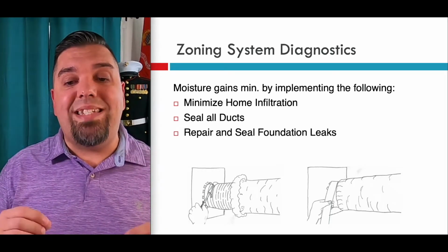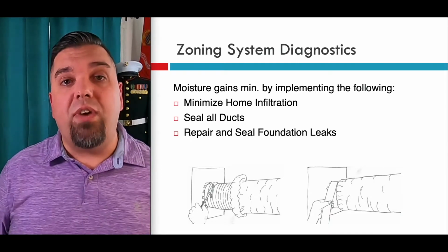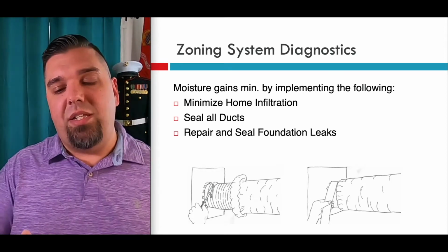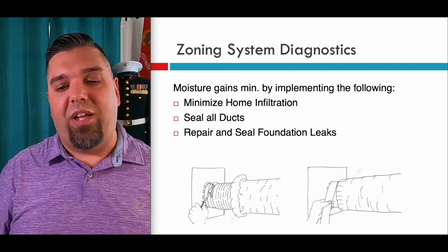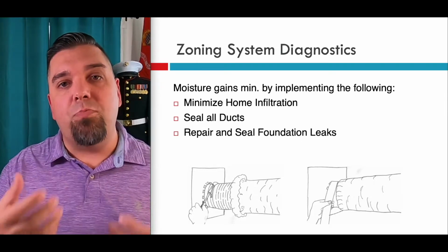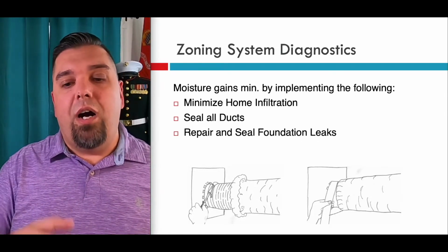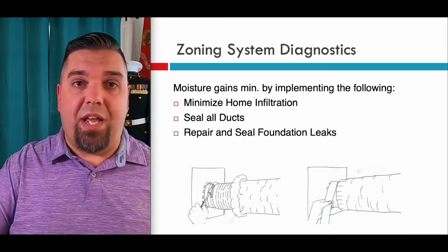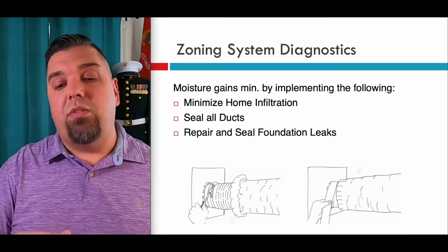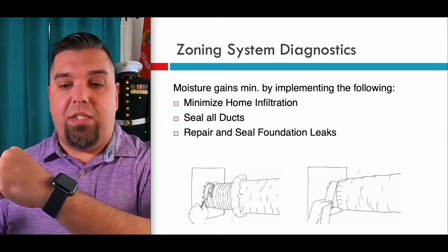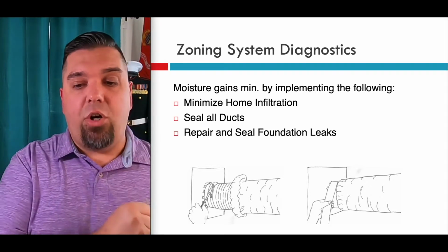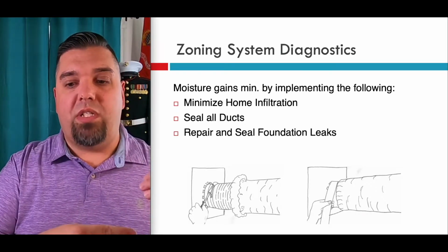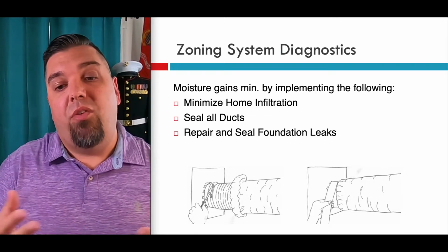Another one is sealing all ductwork and doing it correctly. Just because you have flex duct doesn't mean it's air sealed correctly, right? You can see this is an old image where you have a hose clamp style connection. Obviously, most people use duct ties here. They'll seal that, but you should also paint that with duct sealant, and then pull the insulation back over the connection and seal that to the duct as well. Because if any airflow is moving through the insulation, it's not really effective.